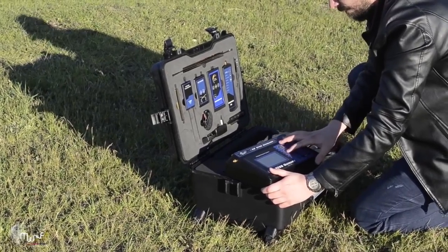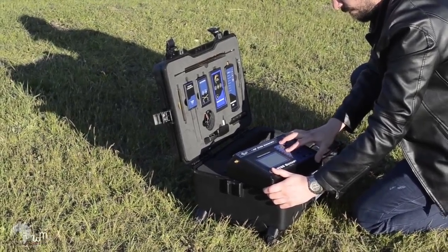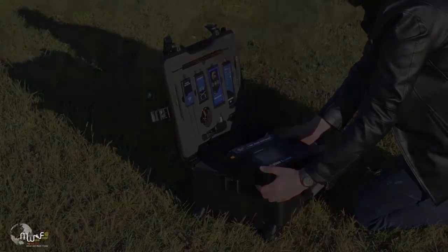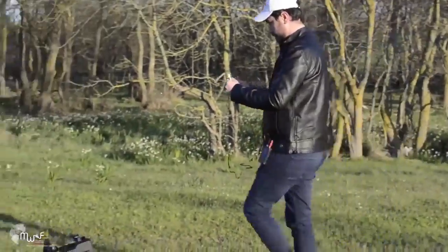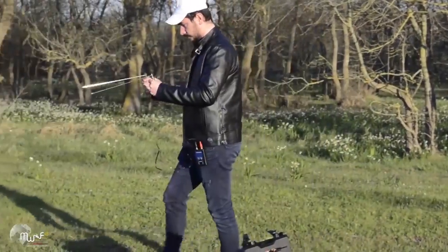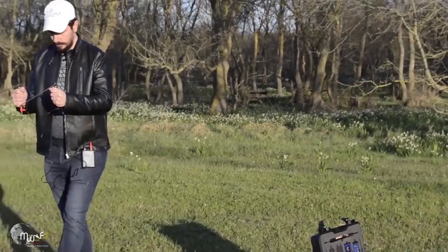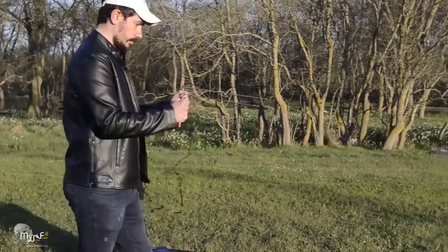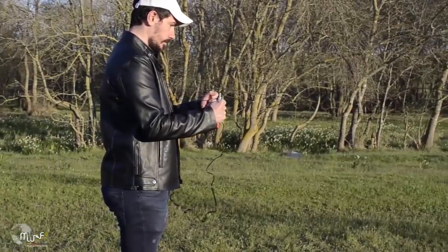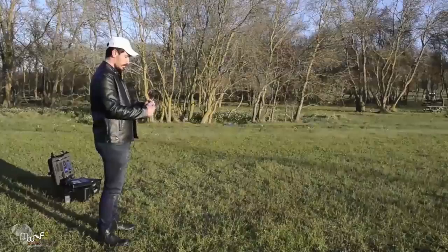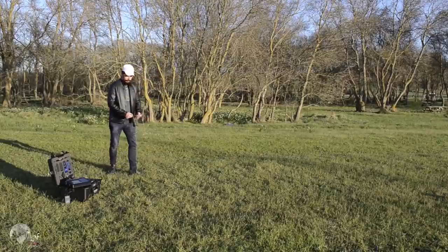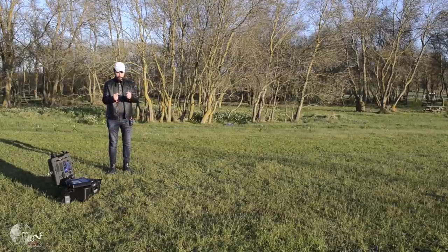Choose the line tracker system from the main unit and assemble the contents of the system as we saw earlier. Then install the receiver on the belt or put it in the pocket. Hold the antennas horizontally, maintaining their balance and spacing between them about 30 cm. Then start walking circularly around the field of the ground transmitter unit that is planted on the ground. Stop at the intersection of the antennas, then move away and change the direction of walking to make sure of the cross point.